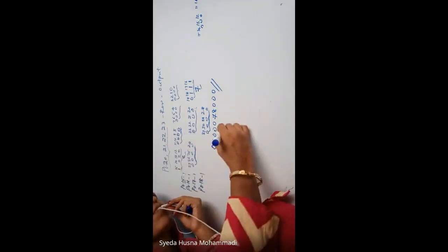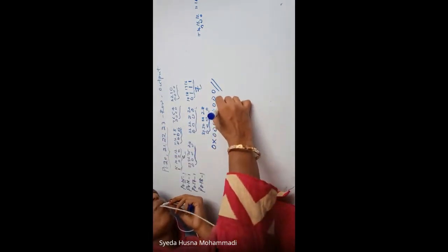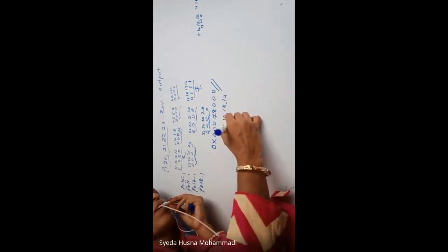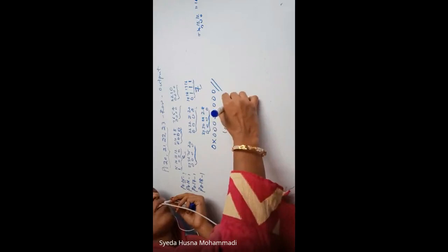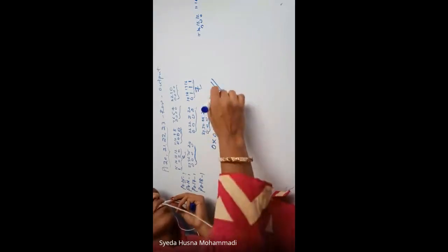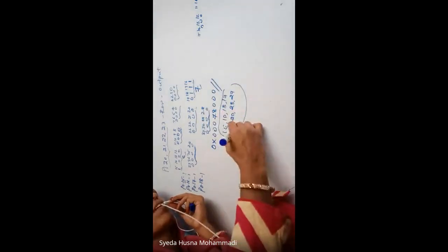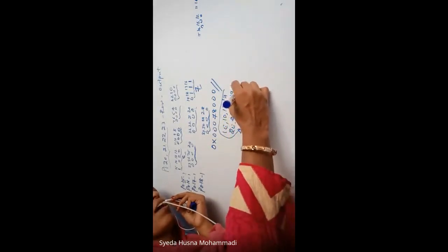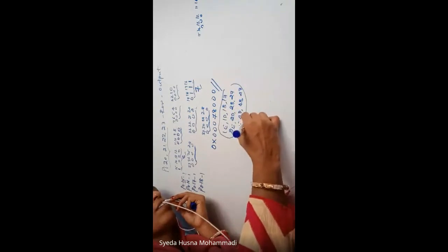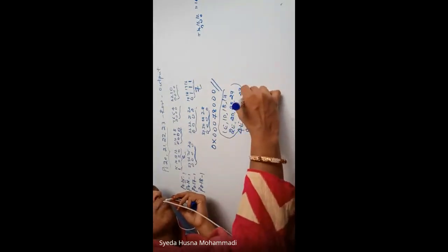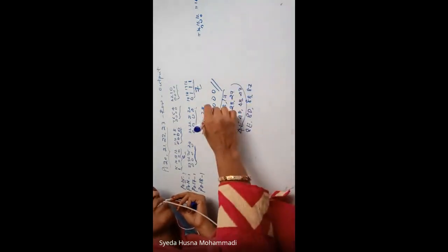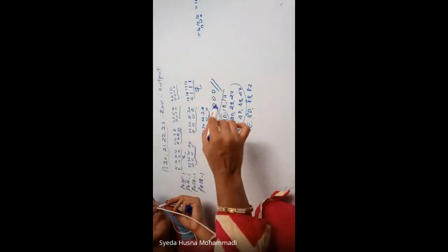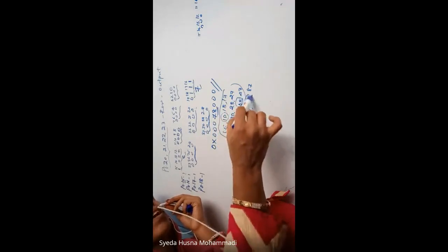This is how we will come to know whether any key is being pressed or not. It will scan with 1E, 1D, 1B, 17. It will scan with 2E, 2D, 2B, 27. If a key is pressed in any of these columns, you'll get values like 4E, 4D, 4B, 47, then 8E, 8D, 8B, 87. If no key has been pressed, the value will be 78. If any one of the keys has been pressed, it will show you 1D or 4B or 8B or something.